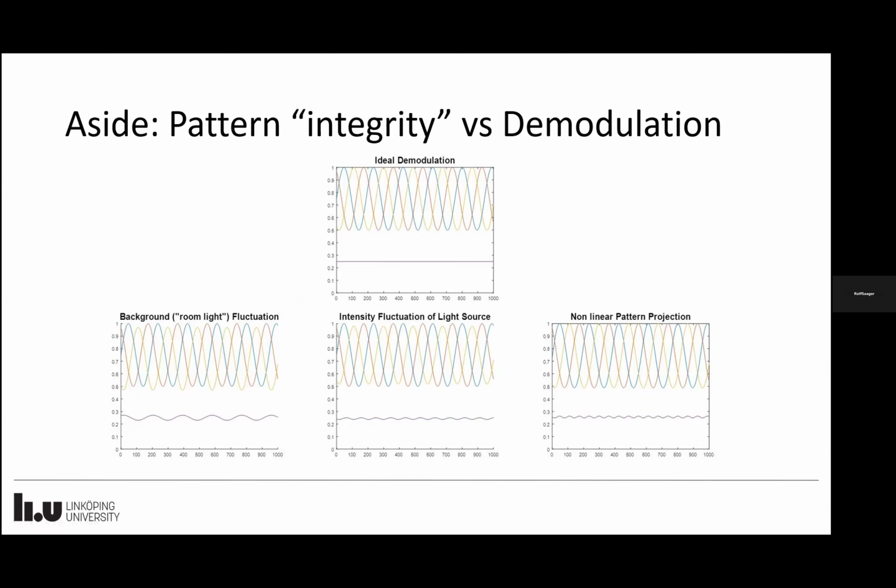You're usually doing 3 phases sequentially. So if you have an LED that is flickering, say 2 phases are of the correct intensity and 1 is slightly lower, you will get residual modulations, but at a different frequency. So you can actually diagnose the problem based on the period of the residual.